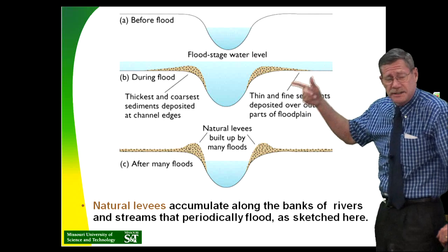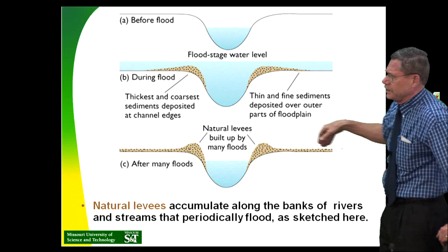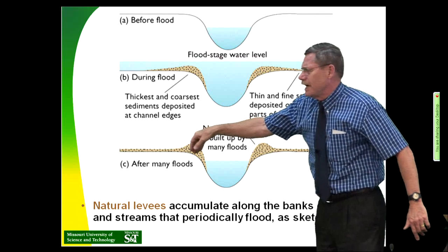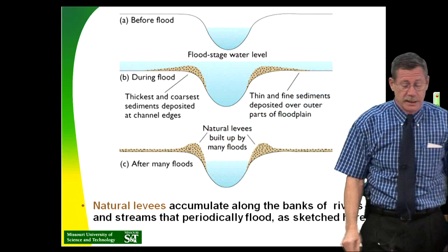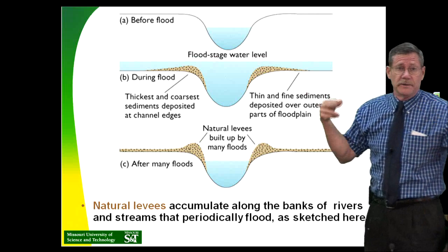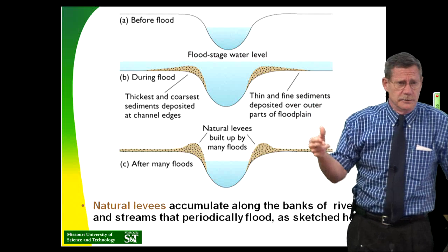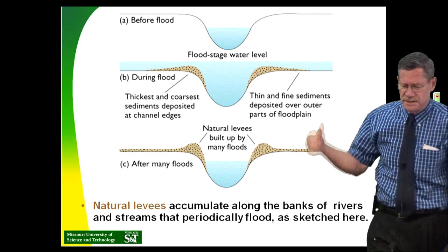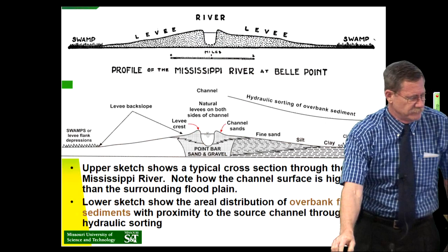They just use common sense on that. So setback levees, a real good idea, and then you use training levees, dikes out here near the active channel, which you sacrifice during the big flows. And you realize you're going to lose them, but you're not going to inundate everybody's neighborhood if you have the setback levee there for the safety.